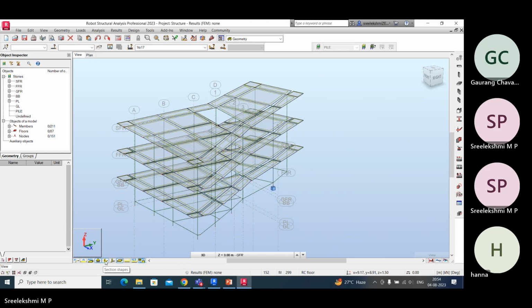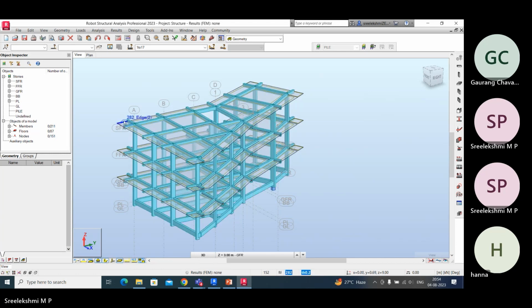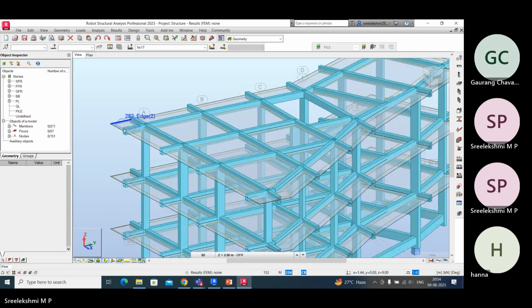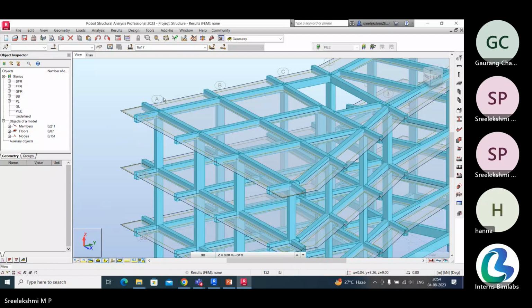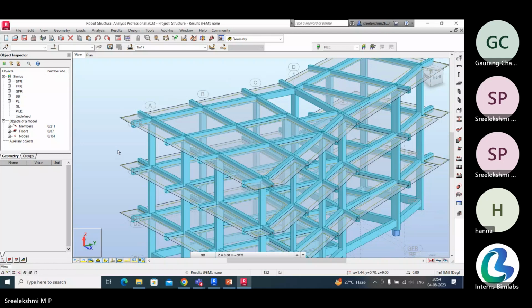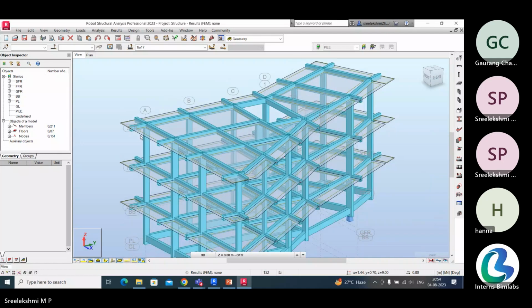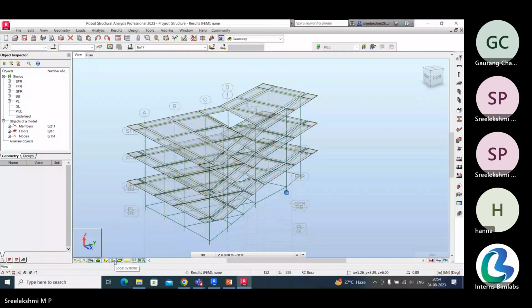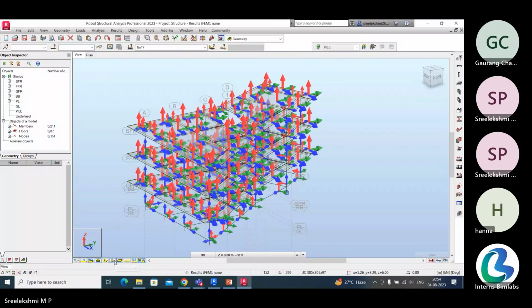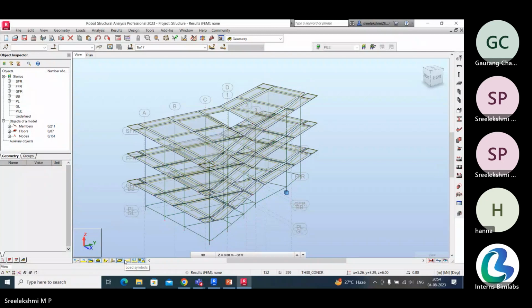And next, about section shapes. Okay, so these are rectangular sections. That's why they are displayed as rectangles. If you are taking a steel model with I sections or channel sections or anything, the section shape should be visible. It's not perfectly a physical model, but almost a physical model. Okay, so next we have local systems, that means the local X, Y, Z axes. Next is panel interiors. If we've given anything, you can see that option, and load symbols. Turn that one off. Then load value descriptions. Okay,